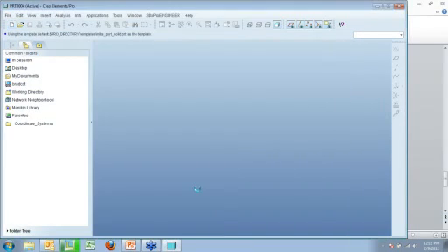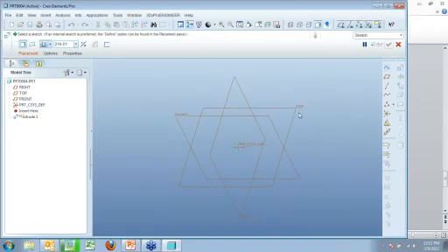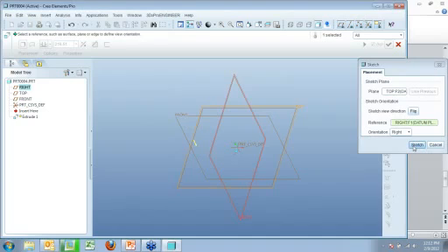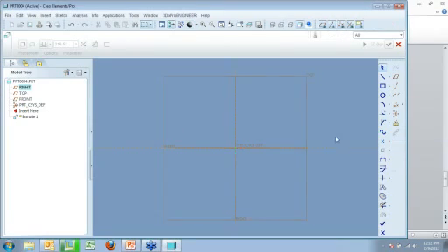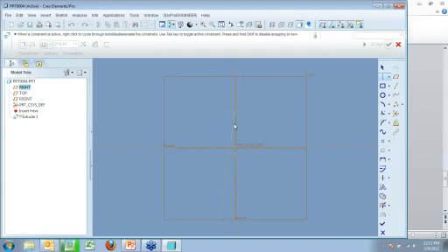So I'm just going to create a simple part. If you guys want to count along the mouse clicks, you can. I counted earlier, it was about 38 or so. Right-click, define internal sketch, select my plane, click Sketch. I'm going to go in, and I want to create some construction center lines to make this square.